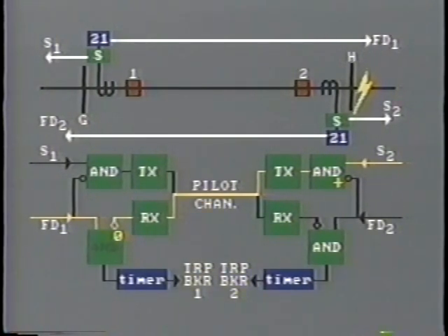As this logic box shows AND, it needs 2 positive input signals, one from the fault detector and one from the receiver. But at this moment, it has only one, that from the fault detector, so the breaker is blocked from tripping by the transmitted signal. To give time for signal transmission and logic circuit operation, the tripping circuit is fitted with a timer. So for this external fault, no tripping would take place.